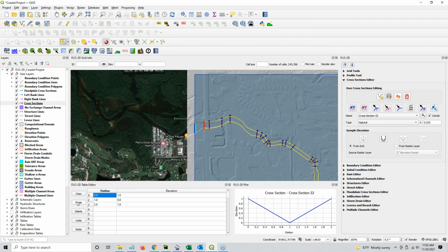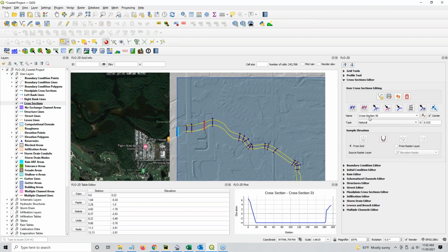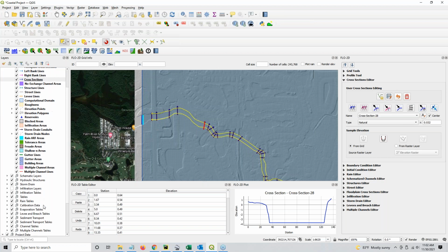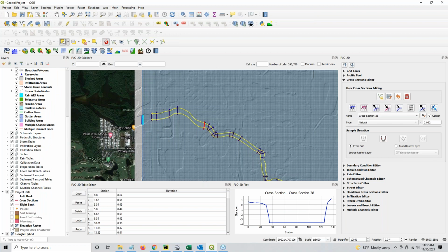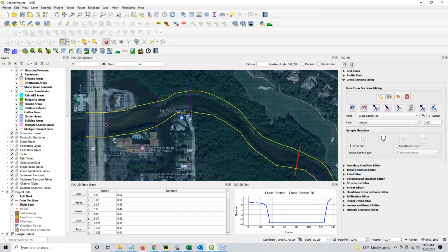And you can see as you go up through here that my cross sections are pretty uniform. If you look at the data in here, I'm going to zoom in here, yeah, there's some sandbars in here for sure. There's some deposits in here. However, these are alluvial sandbars, so they're always reworking themselves, especially when we get high flows coming through here, like from a storm.